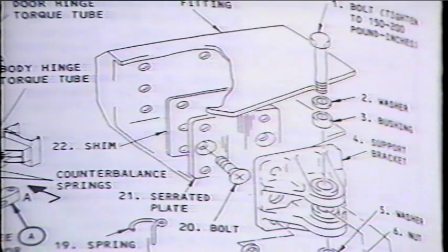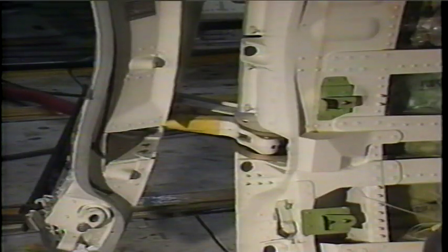If the roller positions are just the opposite, and the forward latch roller is too far from the latch cam, shorten the guide arm slightly. Move the support bracket aft one serration and recheck for simultaneous contact. To avoid the possibility of preloading the guide arm during the initial adjustments, the guide arm must be checked periodically during the rigging for preload. The first check should be done at this time.